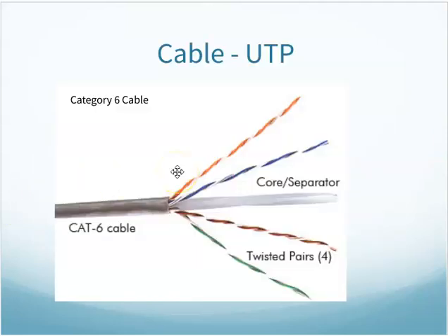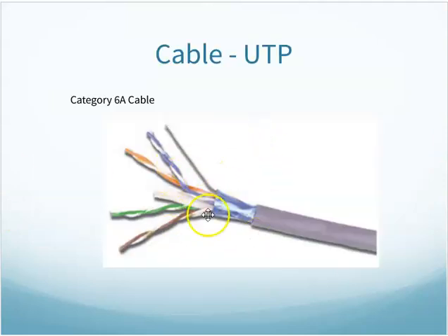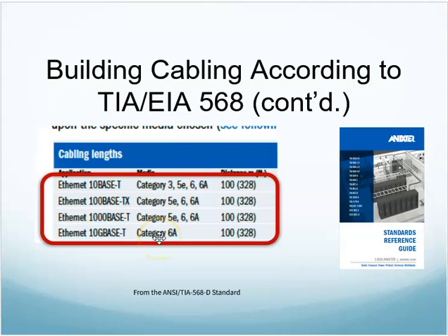As they wanted to put more bandwidth through, again, the structure had to change some more. Category 6, they're now adding a divider between the pairs, trying to reduce the amount of crosstalk or interference between the pairs, if you will. So with category 6, again, you're still able to do the gig, and as they did the 6A and start putting shielding around, this is your screen twisted pair, just the shielding around all 4 pairs, we're now able to dip into the 10 gig category.